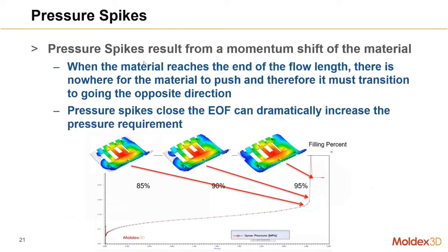All right, pressure spikes in the sprue pressure curve can indicate imbalance. So just a small note here, whenever you have an end of fill region, you can very commonly see a sprue pressure spike. And one thing to note about sprue pressure spikes is they are quite unstable. For example, if I get a sprue pressure spike in reality, the spike might be maybe 40 MPa or so. In simulation, you might see that that's like 60 to 70 MPa.